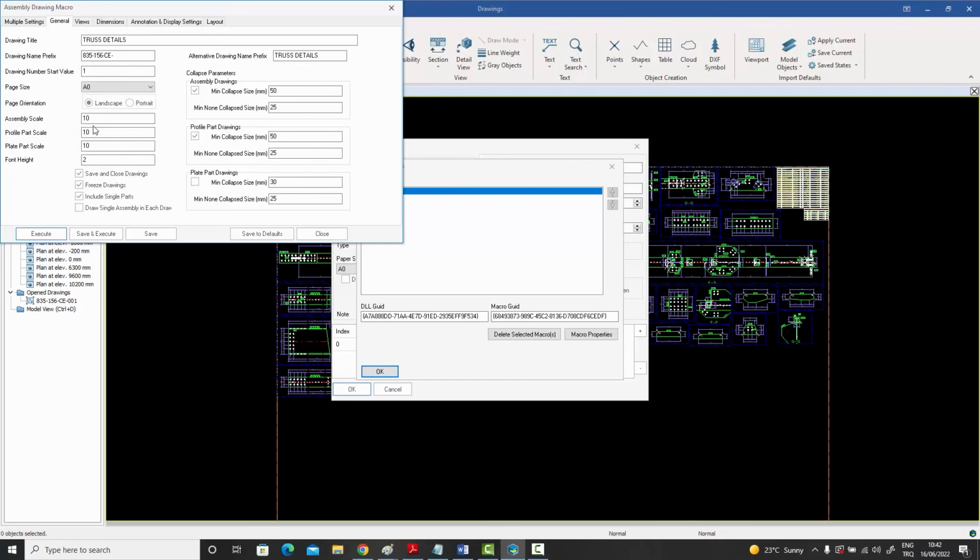So you can have all beams starting with B, the drawings will be created according to this rule, but you can give that particular beam a special mark. So let's call it the special beam, SPB, and the SPB will be dimensioned differently. So maybe the SPBs are very large beams, and you want them to be dimensioned or drawn differently.